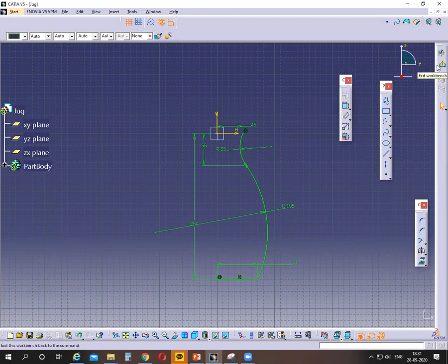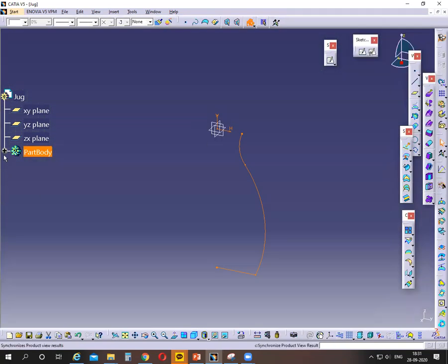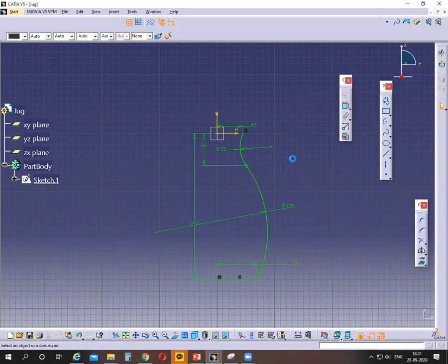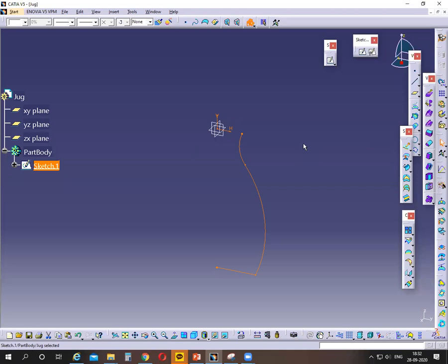Okay, you can use a revolve surface. Here in revolve, you can draw a center line touching the vertical axis. You can draw the center line along the vertical axis, then you don't need to select the revolution axis. But if you don't draw the center line, the center line is the default revolution axis. So if you don't draw the center line, then you have to select the vertical axis as the revolution axis.